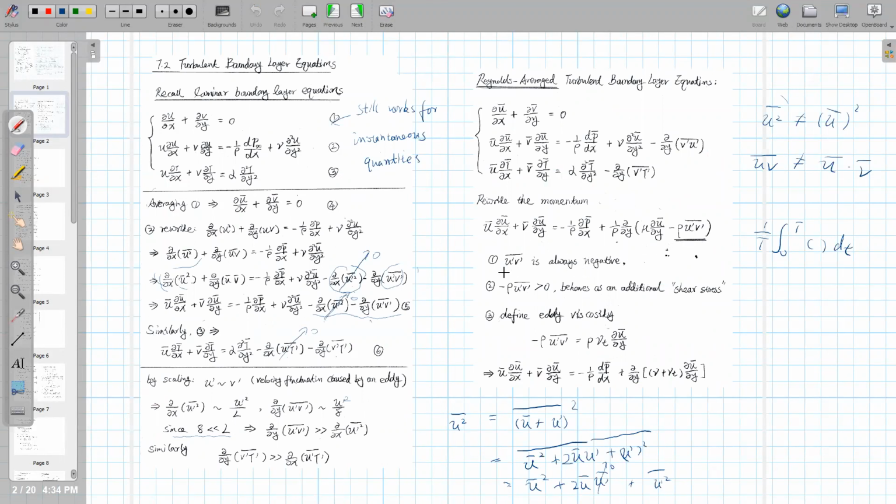You need to know that this additional Reynolds stress term is basically a correlation between V prime and U prime, these fluctuating quantities. This quantity is usually negative. We always consider it a negative value, which statistically means the correlation between U prime and V prime. There is a way to prove this mathematically, but another easy way to think about it is that U prime is the velocity fluctuation in the x direction, and V prime is the fluctuation in the y direction.